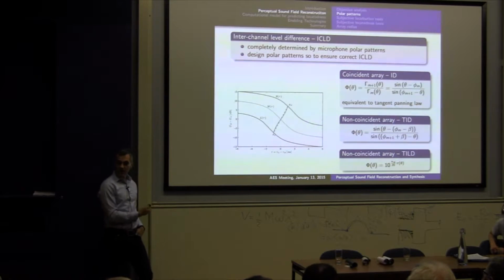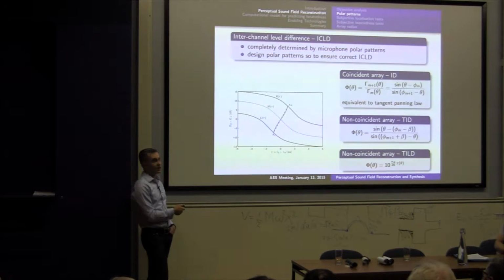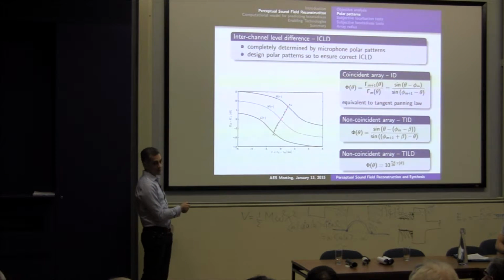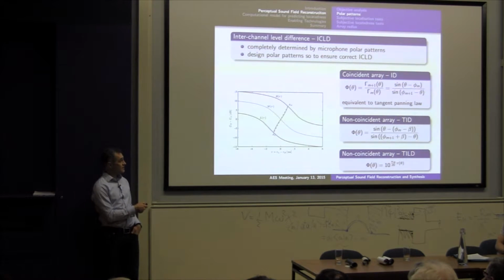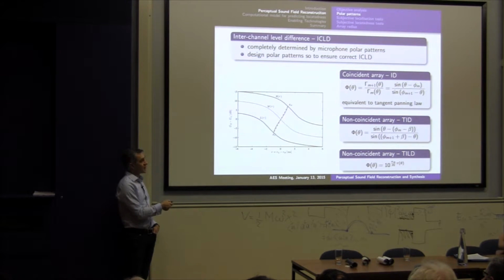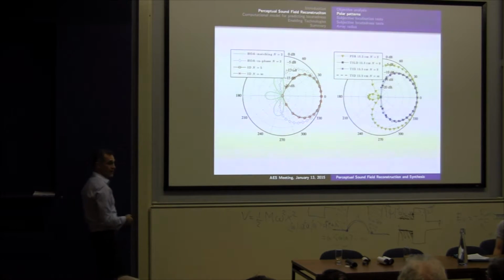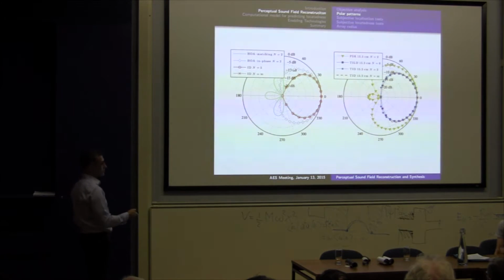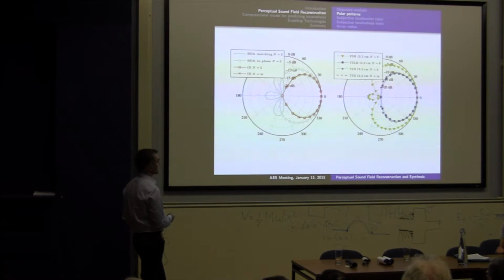It turns out that implementing a straight line would require higher order microphones than is practical. Then we tried something with second order polar patterns, and that is what we obtained. It turns out that in acoustic experiments, this also gave better results than just a straight line. So which exact line to take is still an open question, but it doesn't seem to make too much difference as long as we have some monotonic line going from one endpoint to another. Here we have some closed form expressions for this. I'm not going to go into details, but that's described in our papers.